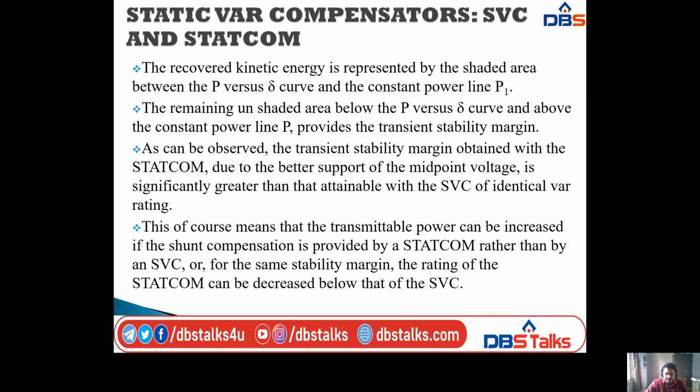So this of course means that the transmittable power can be increased if the shunt compensation is provided by a STATCOM rather than by an SVC. So for the same stability margin, the rating of the STATCOM can be decreased below that of the SVC.